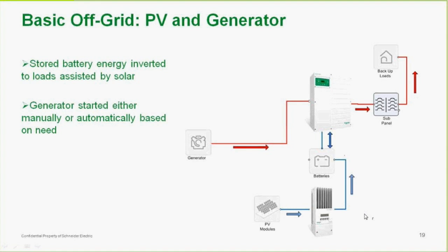But in the solar industry, when we say AC coupling or DC coupling, what we mean specifically is that the array is tied through its regulation to the batteries, or really, correctly, you might say, to the DC bus. So this would be a DC coupled system, basic off-grid.